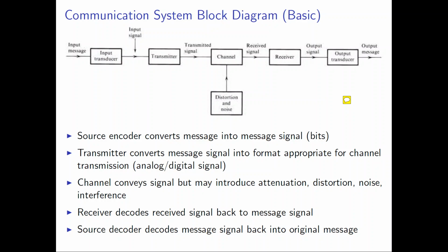And at the transmitter you have your data, which is in analog format. You try to convert it to bits, and then you prepare the bits in a waveform or in a shape that is suitable to be transmitted over the air. And the receiver's job is to receive the signal that's corrupted by many impairments and many drawbacks caused by the channel and get back your original data bits. So this is the basic.